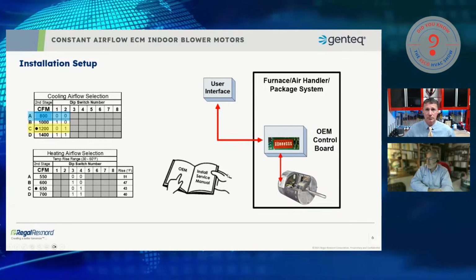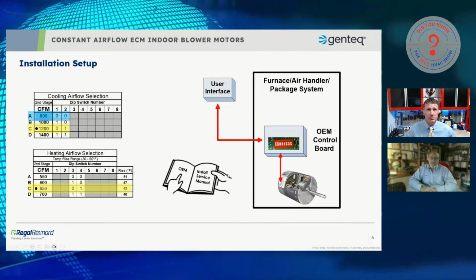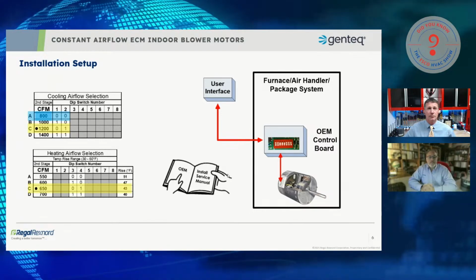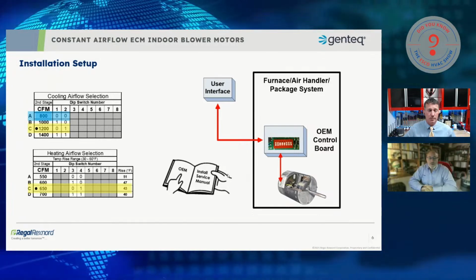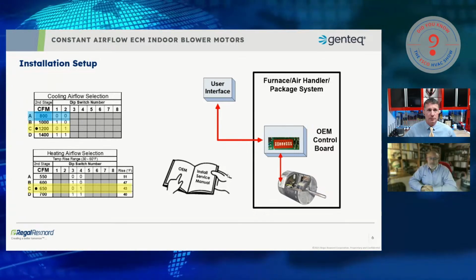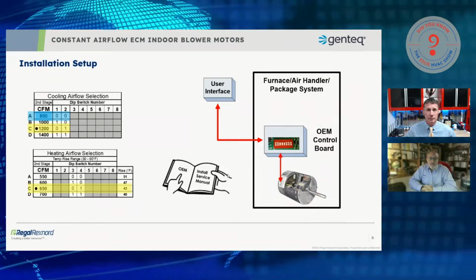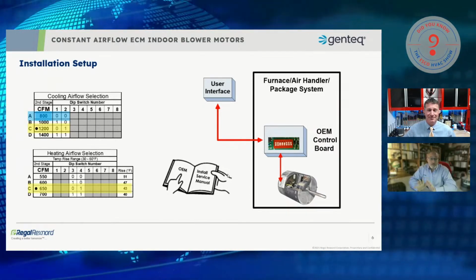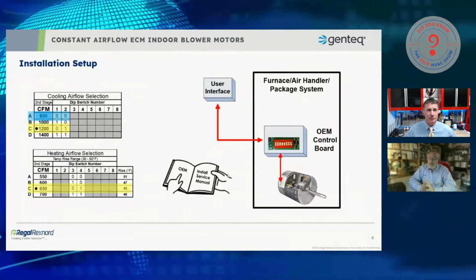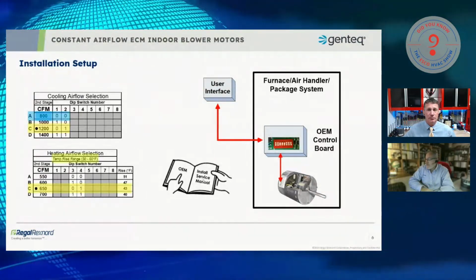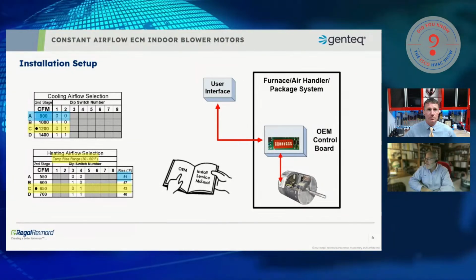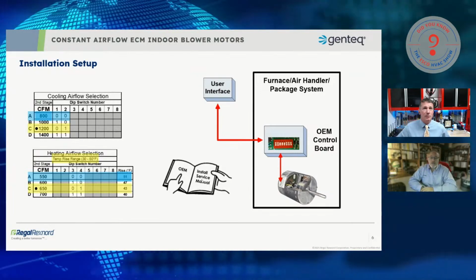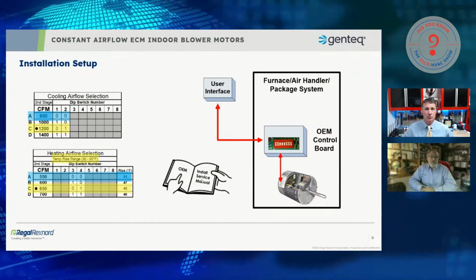Absolutely, that's true, but as I mentioned before, you're going to take out a 70% efficient Chrysler Airtemp that had a temperature rise of 70 to 100 degrees, and you're going to put in a 95% two-stage that has a temperature rise of 35 to 65. The customer is going to complain, boy, that air is a little cool, especially in first stage. Here, if I flip one dip switch, I can get, what is it, 43 to 51 temperature rise. I can get 8 degrees more temperature,